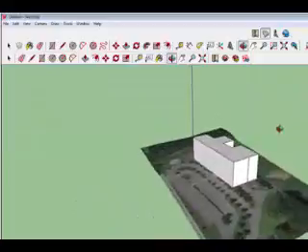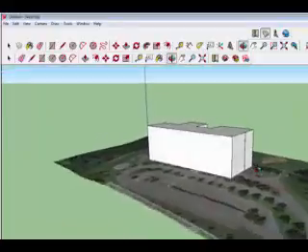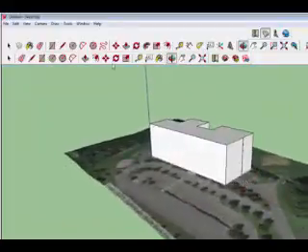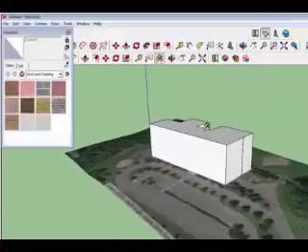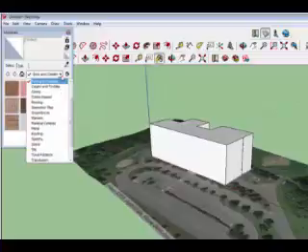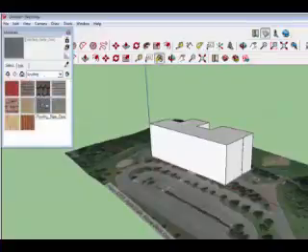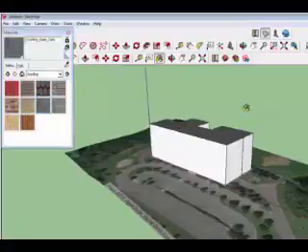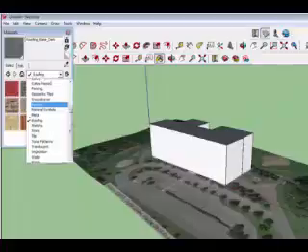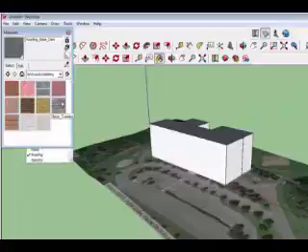Then what you can do to get really fancy is you can color things in. So if I color, and you can pick brick cladding, so let's do roofing. And so let's say we have a black roof, and you can now do siding, or let's say bricks and clad. Let's say the building was brick.